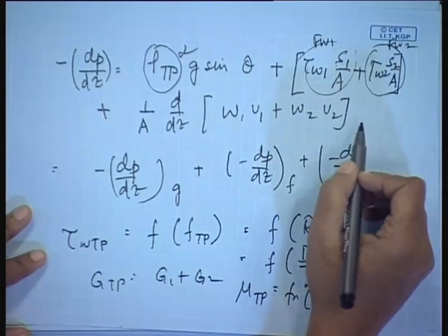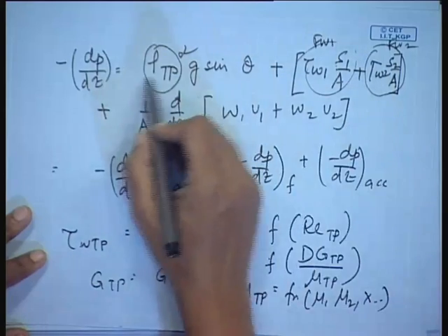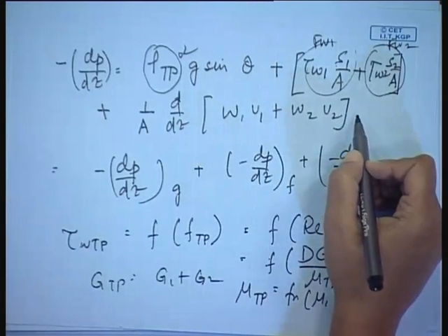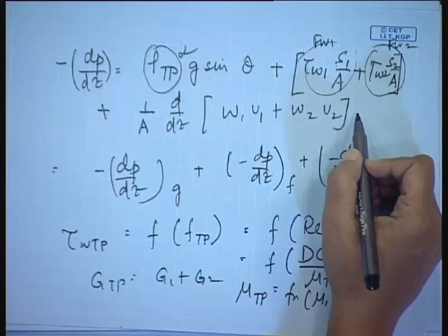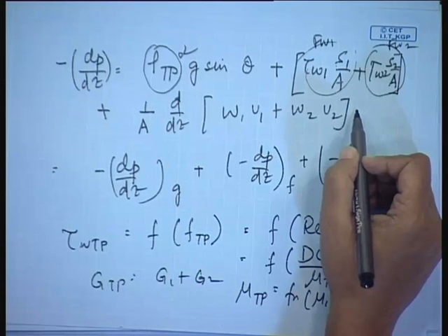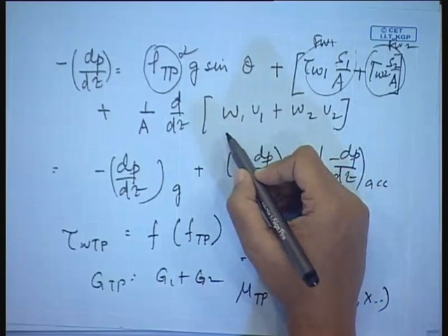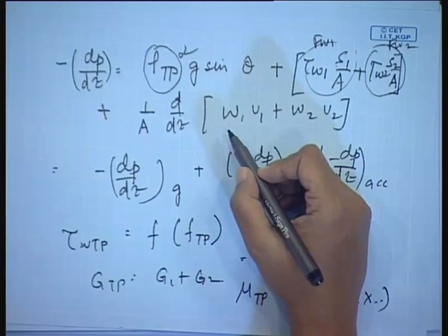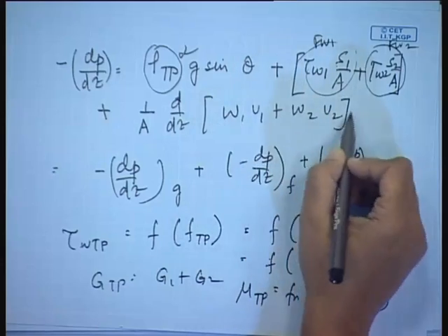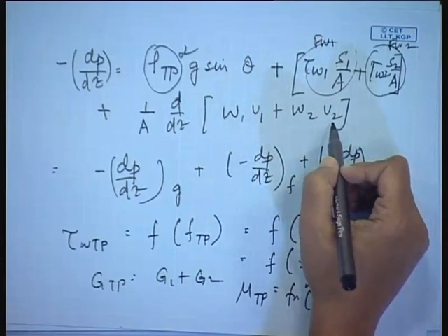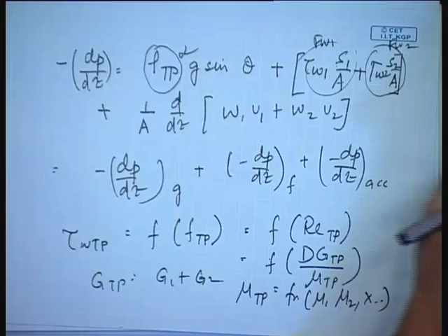Okay. So, first we will try to derive this equation in a form which will enable us to find out the pressure drop from known input parameters. For that, we will be dealing with the acceleration pressure gradient just as we had done for the homogeneous flow theory. Now, whenever we try to expand this U1, U2, normally we get some terms containing dP dz, isn't it? Why? Because V1, V2 etc. they vary with pressure.